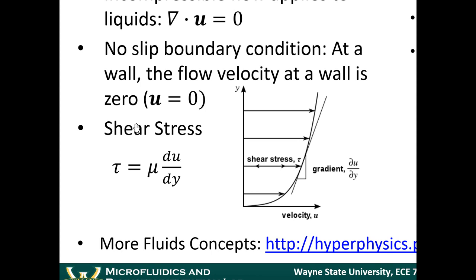Okay, in a small pipe, you're always closer to the wall, right? So you have more interactions with the wall. These velocity gradients always arise near the wall. And so the shear stresses arise near the wall. So this is one of the reasons you end up having more shear stresses in a microfluidic device than you would have in a large-scale device.